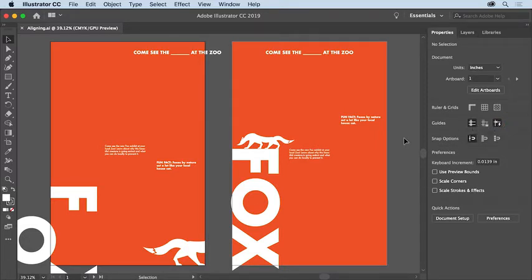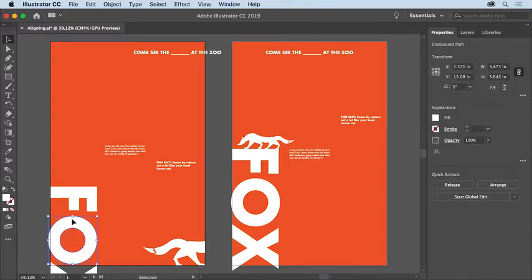Smart guides are temporary guides that are helpful when you move and align content. With the Selection tool selected, in the poster on the left, drag this O shape to the right. As you drag, you'll see magenta lines appear. The line you see in the middle of the shape means it's staying aligned with its original position. Now, if you drag far enough to the right, you'll see a vertical alignment guide on the right edge when it's aligned with the other letters. When you see this, release the mouse button.